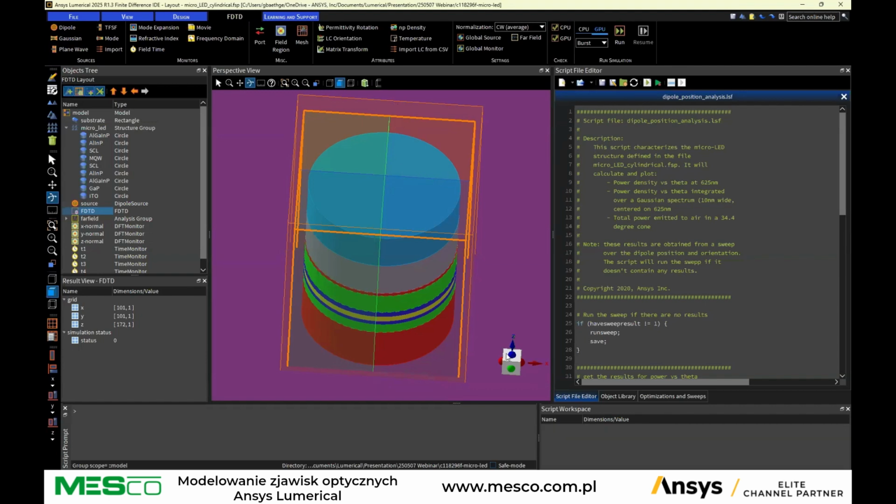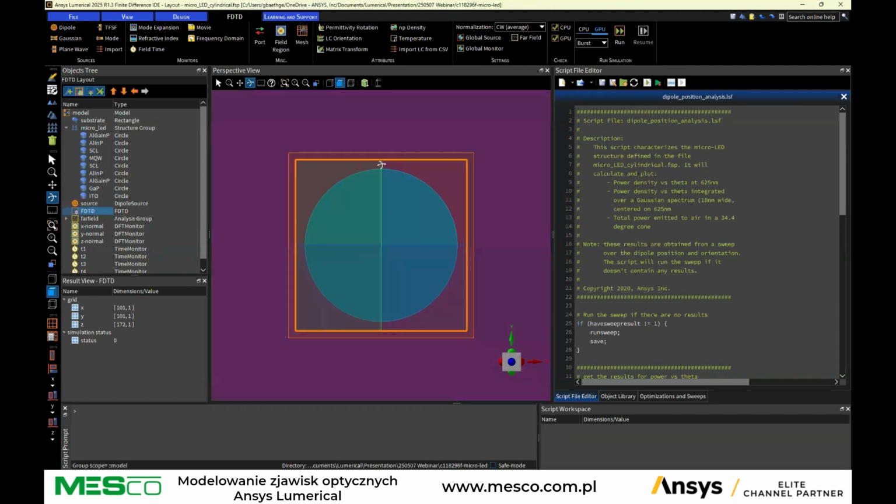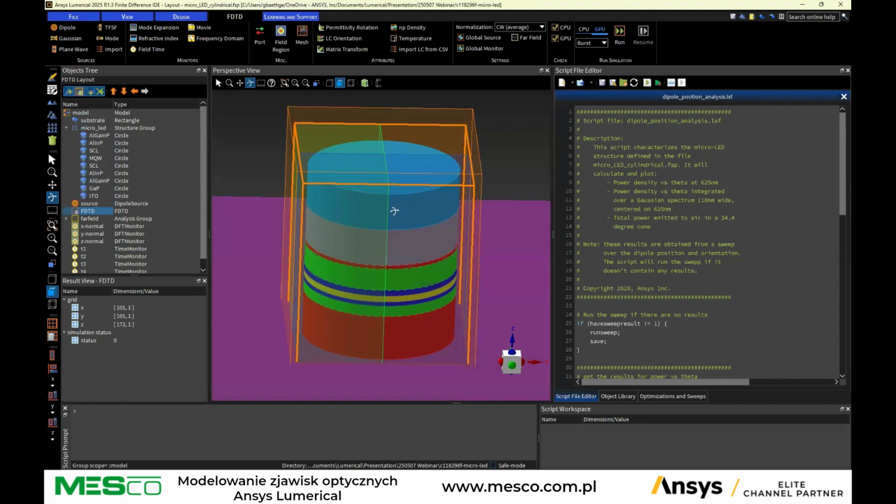In practice, we simply model a quarter of the simulation volume, this top right corner here. When we get the results out of the simulation, these results from one quarter of the simulation are automatically unfolded based on the symmetries that we used here. That's very efficient to reduce the simulation volume and obviously the simulation time.